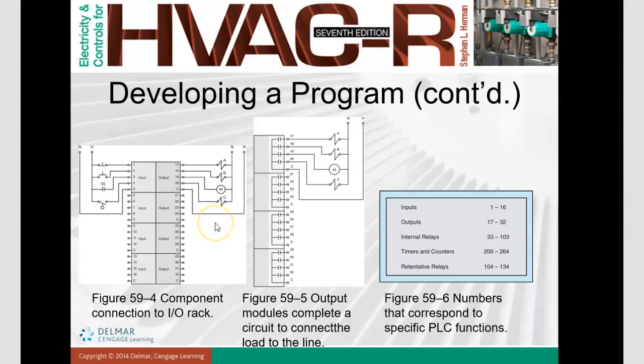Okay, how do you want to know whether this is input or not? So just by looking at the relay schematic before this. Okay, for example, here we know that the start stop button, push button, and normally close or normally open switch, all are inputs, because we have to push it.